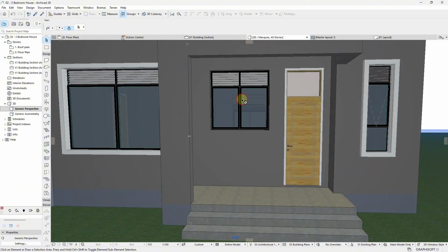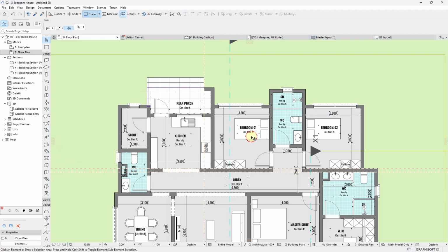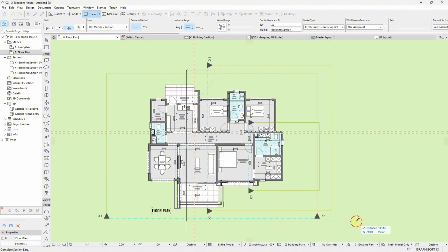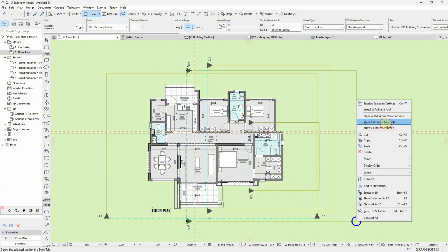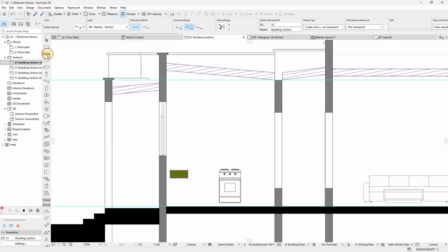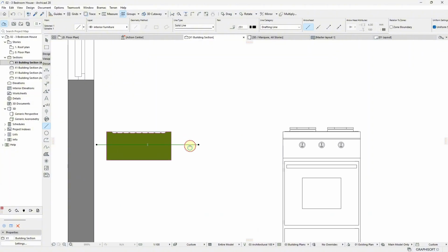And then also, for kitchen windows, always make sure to come and check the height here, because in most cases we do our sinks or the worktops at 900. So if this is your kitchen, the worktop is going to be here, so you make sure that this height is at 900 or 1 meter, okay, let's say 1 meter at least.